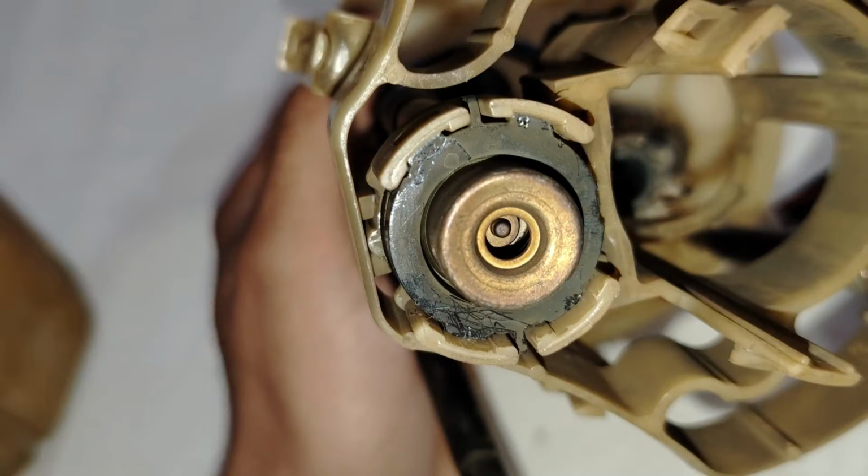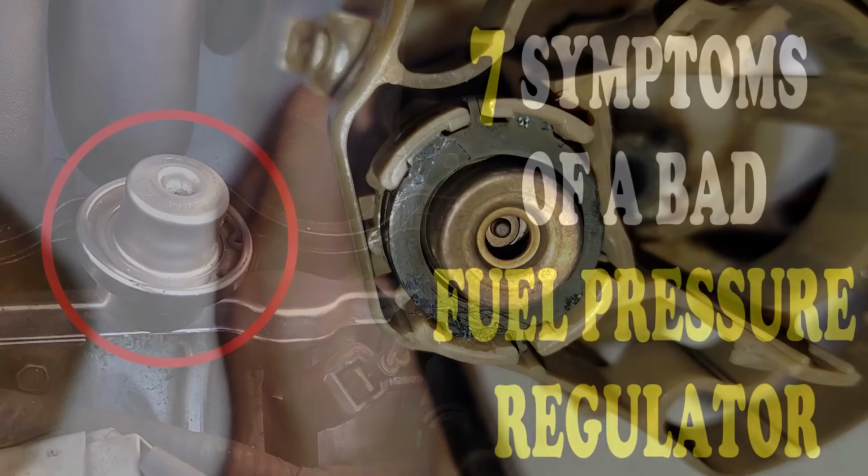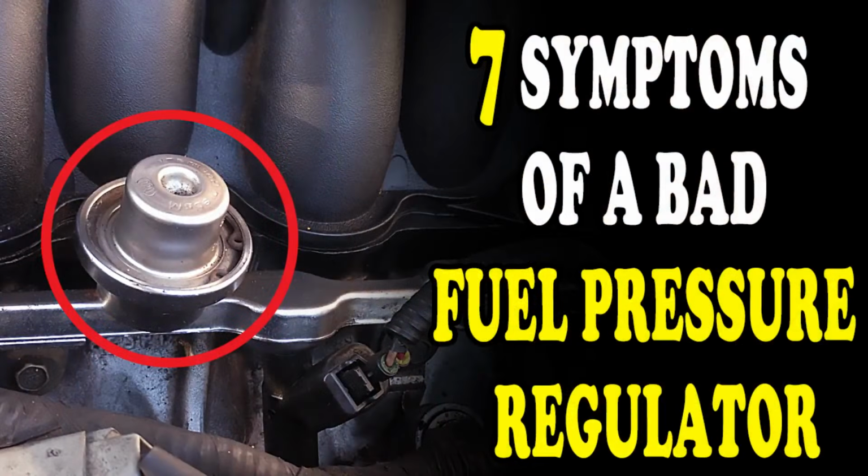You can diagnose this fault by measuring fuel pump pressure using a fuel pressure gauge. We previously discussed all fuel pressure regulator failure symptoms in a dedicated video. Link in the description below.